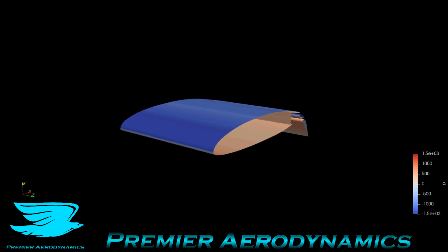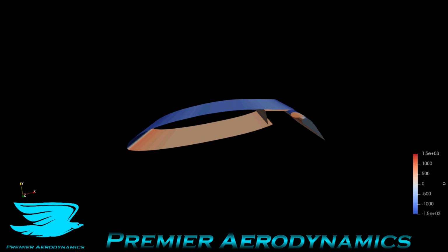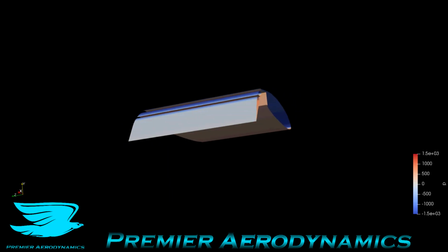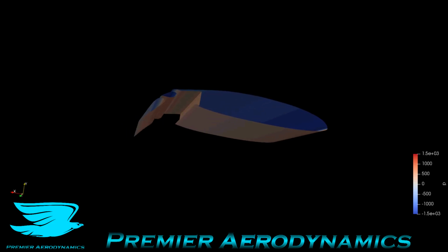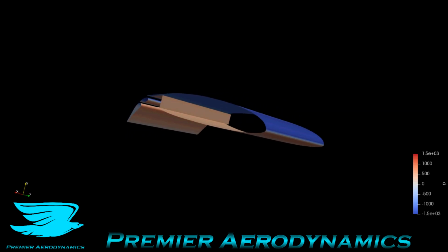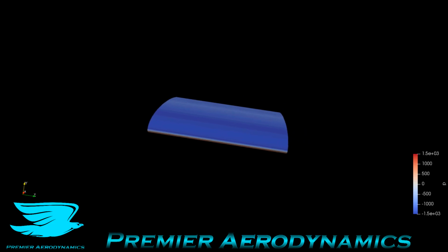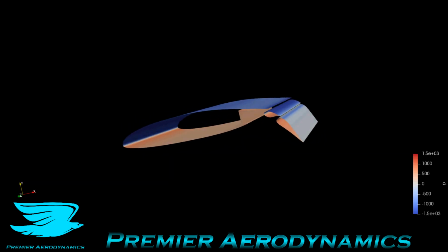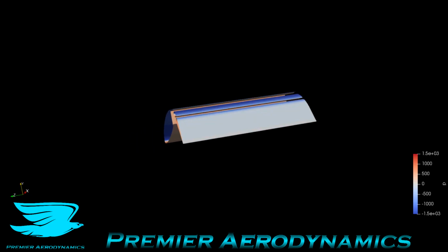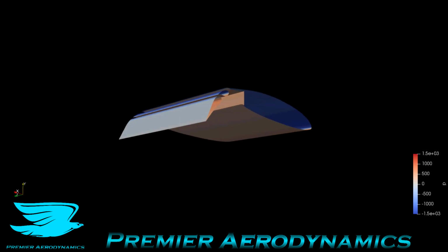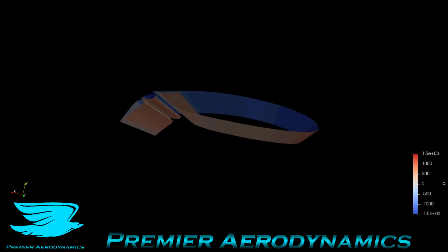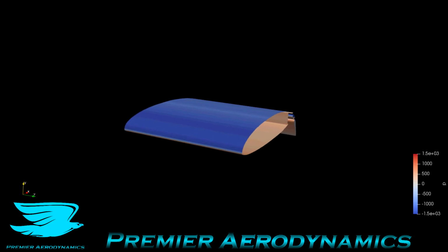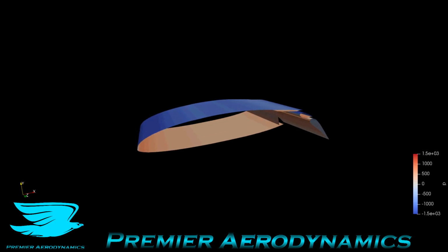The good thing is that you can see that each one of these airfoil sections is producing lift by itself. So you know how I mentioned in the other video that the third element is in stall, but there is still a little bit of lift being produced, and you can see that here with the pressure gradients. So what does this mean? It means that because we are introducing additional air in between these little vents here, these little slots, we can treat each airfoil as effectively a separate lifting surface and still produce lift, so the entire system can reach such a high lift coefficient of 3.2.